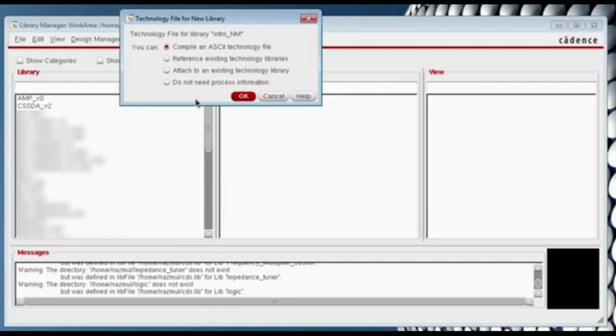It is the heart of the IC design process because these files are given to the IC design engineer by the semiconductor foundries such as IBM, TSMC, and GlobalFoundries, and many more. Using the PDK transistors and other elements, the design engineer makes the IC and finally submits the final design to the fab companies for chip fabrication.